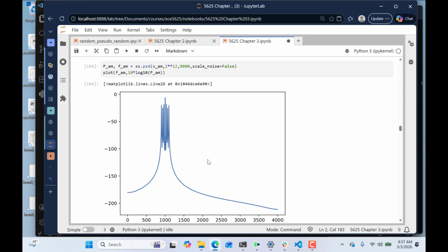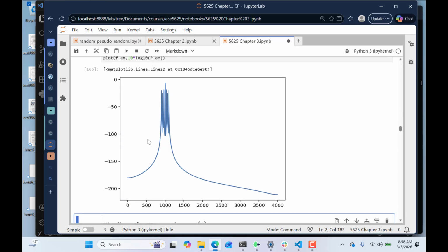And there it is. I don't like the looks of my axes plotting, though. This is all just washed down here from the FFT and the fact that I don't have noise present. So whenever you see something like this, don't give that to me. And some of you, I said zoom on the horizontal axis when you're doing the pulse shaping because you wanted to see the spectra of the root raised cosine pulse shape. Here we have way too much dynamic range to really be useful. This is just artifacts from the FFT or the transform. So I'd probably drop this down to maybe -80.